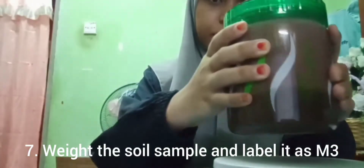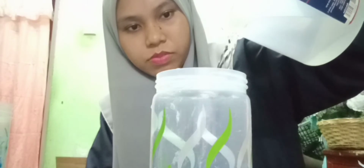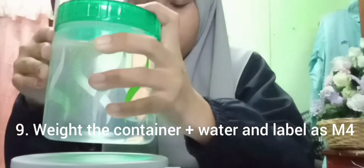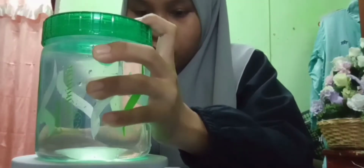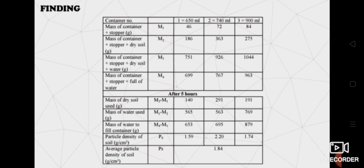After that, weigh the soil sample and label it as M3. Fill with water until full. Lastly, weigh the container plus water and label it as M4. While finding the particle density, I got an average particle density of soil of 1.84.